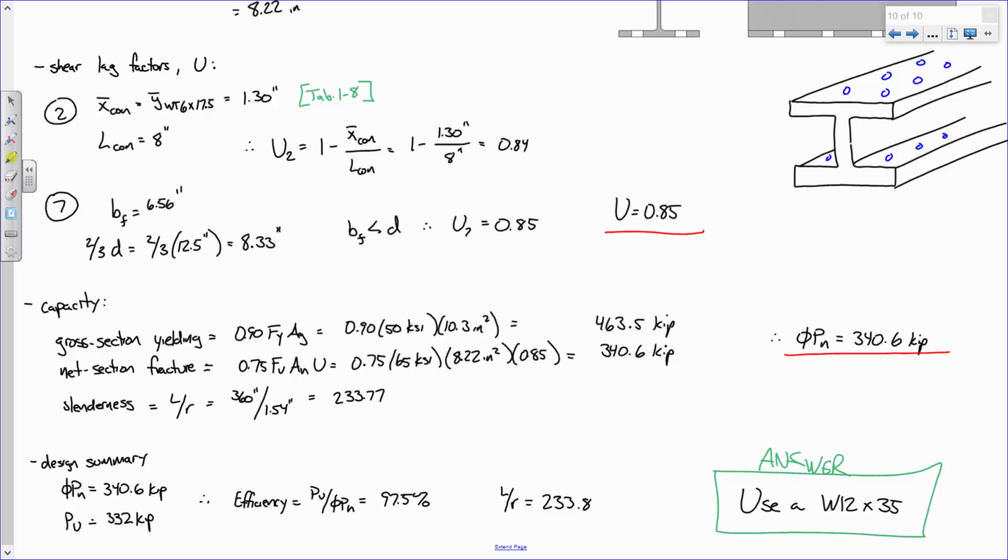Nowadays, when you build a new bridge, the idea is to cast what's called an integral abutment. So you have your beam, and when you pour your concrete, all of this concrete is all one pour. So you're trying to eliminate that actual separation. It's called an integral abutment. They do that to eliminate that joint because expansion joints suck. They always fail.